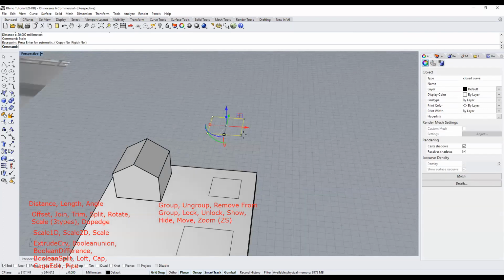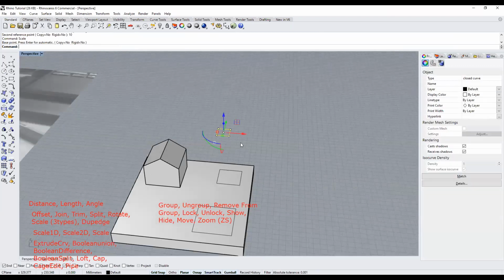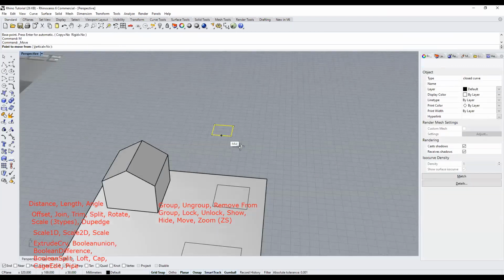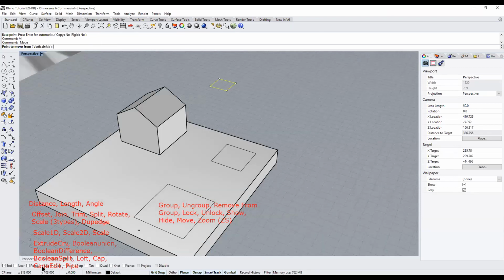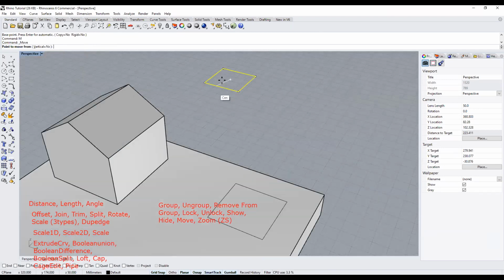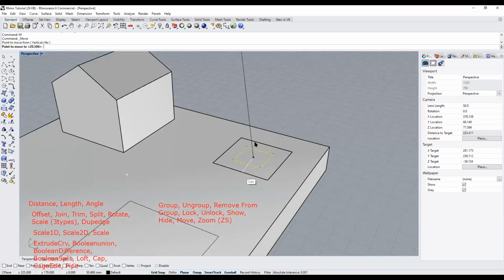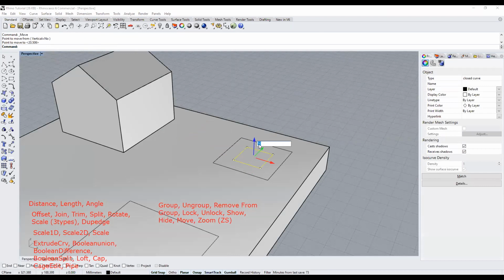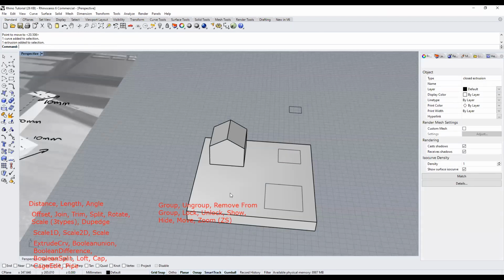Actually, I'm just gonna scale it. So it's 10 millimeters by 10 millimeters. I want to make sure that the center of this aligns to the center of this. I'm just gonna turn off mid and all those points for now, and I'll turn on center object snap. So I'll snap the center of this curve to the center of this curve, and then move it up by 50. Once I'm done, I will use loft to create a surface between these two curves.